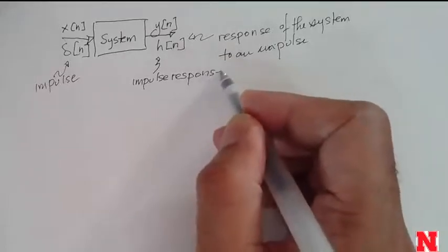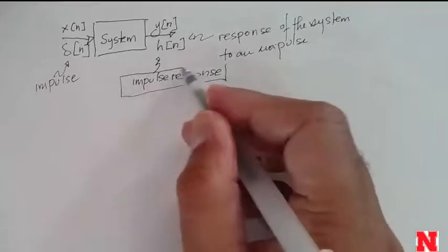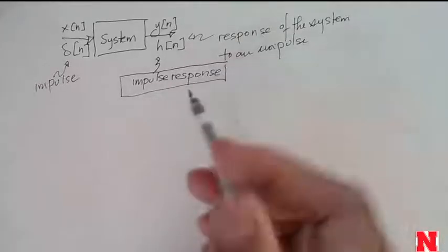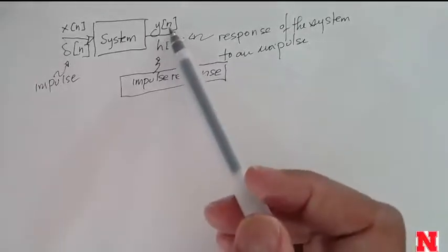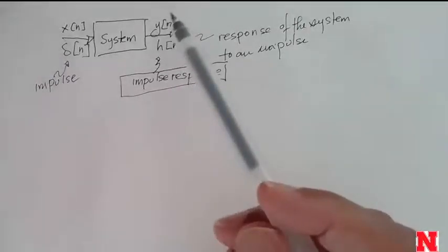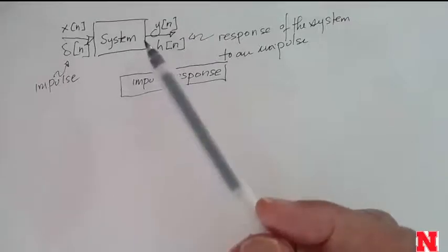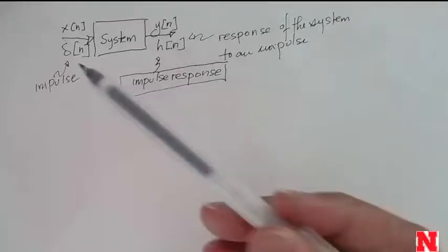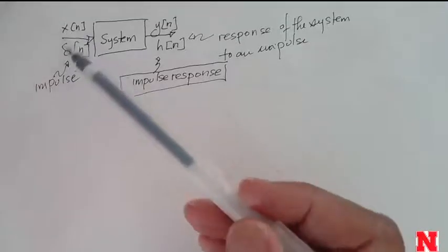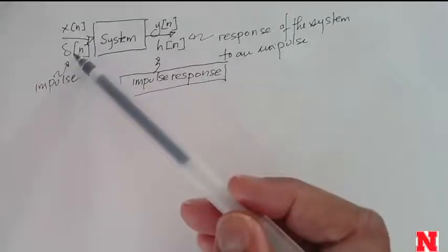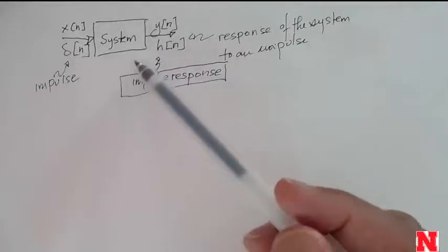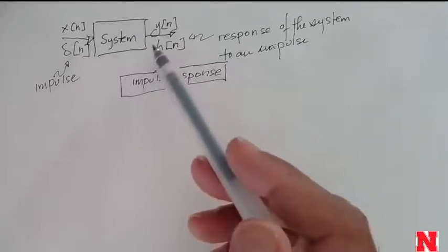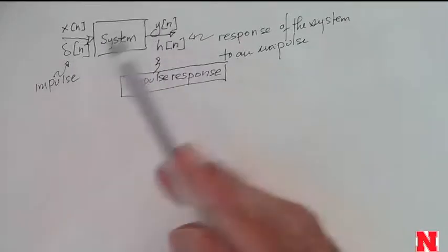Engineers are pretty straightforward people. I mean, all our nomenclature is kind of like that. It's very, very simple, right? But do remember this, because I'm going to give you an input-output relationship and ask, what is the impulse response? And you can find that really easily by taking the input and replacing it with an impulse function, a delta function. Now we're just doing this for a discrete time system because it's easier to see, and then we'll go ahead and do this for a continuous time system as well.